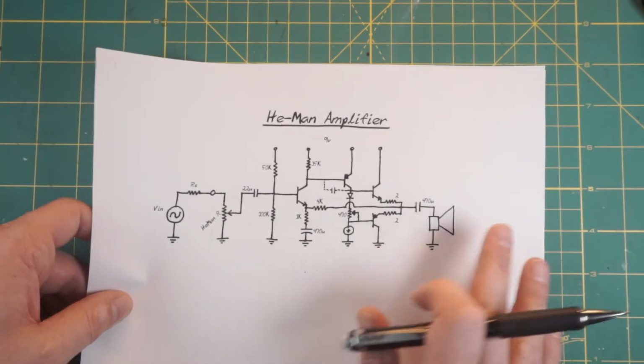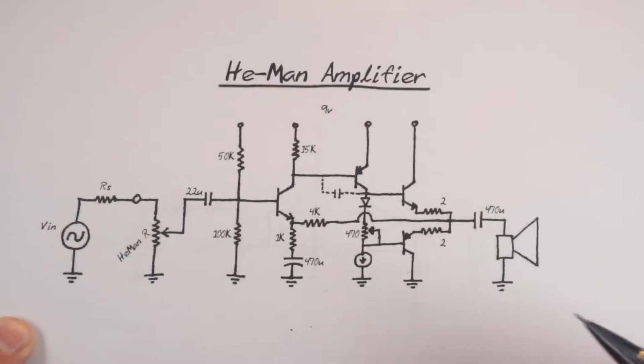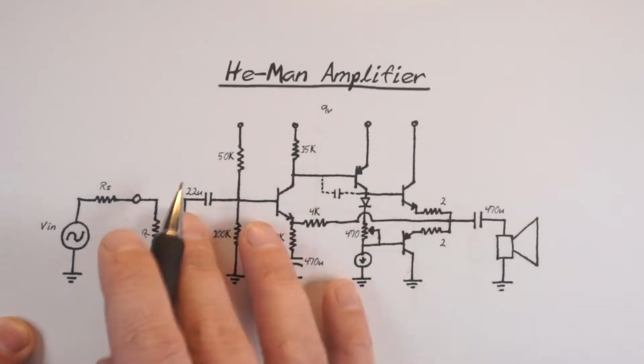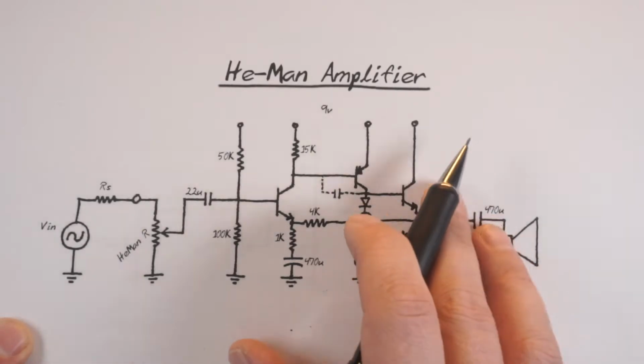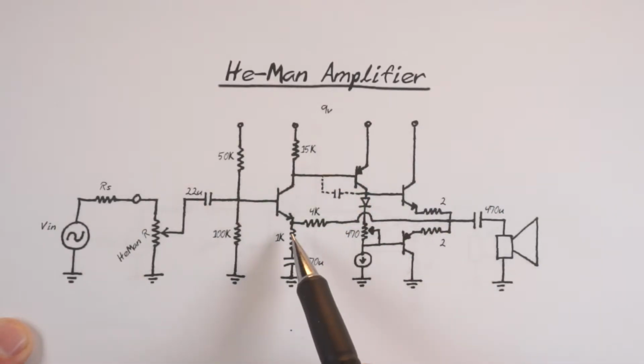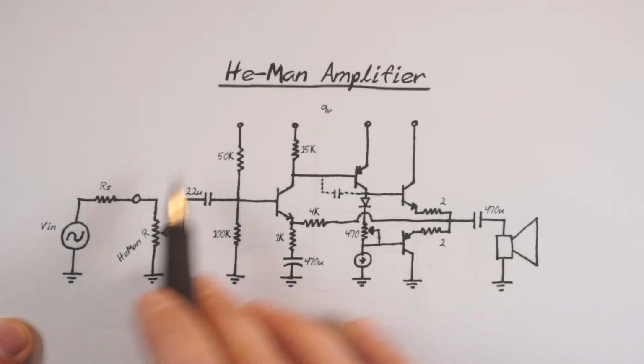Okay, so here's the circuit again. What I needed is an amplifier that has a high input impedance, a low output impedance, and a voltage gain of say 5-ish. I also wanted a large open loop gain so that when I apply feedback, I can improve the linearity of the amp.